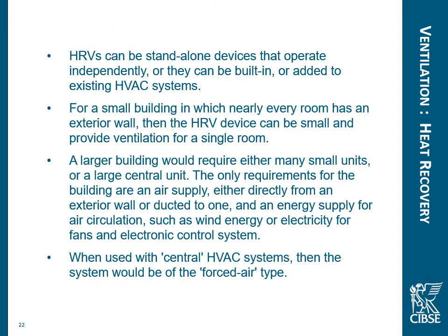Well, heat recovery devices can be standalone devices that operate independently, or they can be built in or added to existing HVAC systems. Now, in a small building in which every room has an exterior wall or has access to an exterior wall, a heat recovery device can be a small standalone unit, perhaps in the roof space or perhaps in an adjacent room. A large building will require either many small units or a large unit connected to the centralized system.